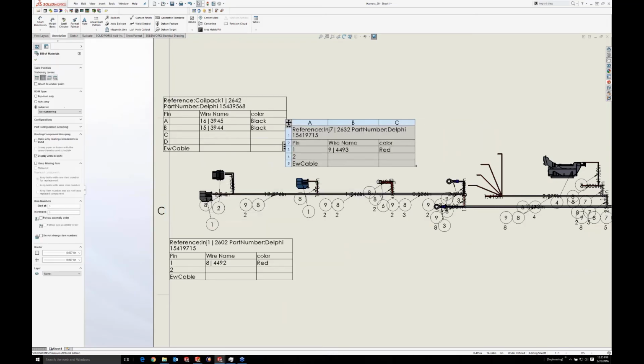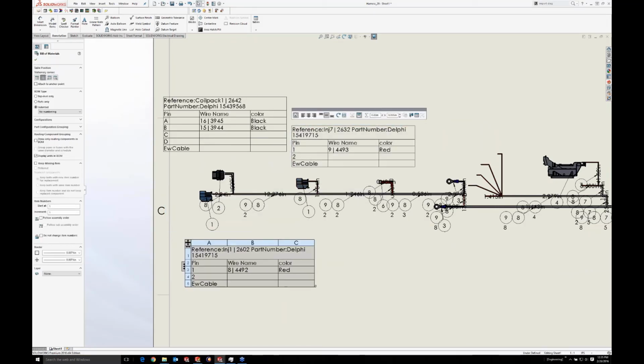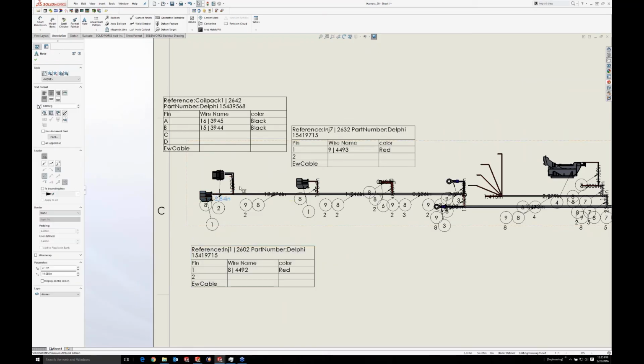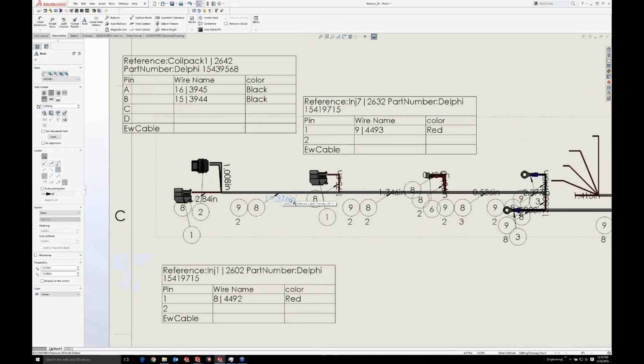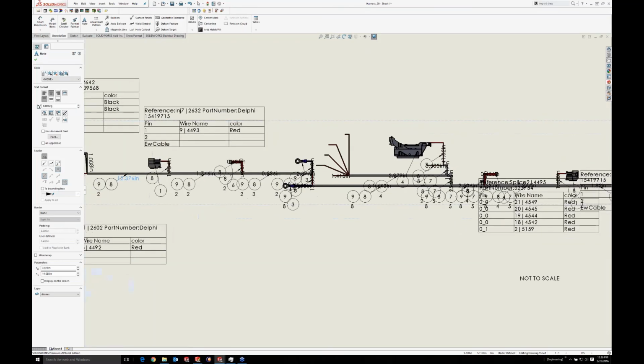This is an injector wire and an injector wire. And these are ballooned and tagged for length. I have it set to tag down to the 1,000th. This section, we were talking about, how much covering do I need and all that. You can see SOLIDWORKS Electrical does understand exactly how thick this section is. It has ballooned, saying you have 2 wire 9s and 1 wire 8 in here. And it said it's exactly 12 and 3/8 long.